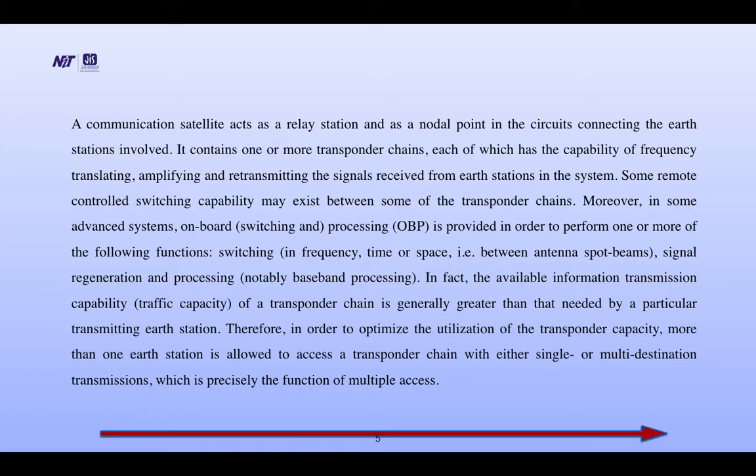Moreover, in some advanced systems, onboard switching and processing, OBP, is provided in order to perform one or more of the following functions: switching in frequency, time or space, that is, between frequency or antenna spot beams; signal regeneration and processing, notably baseband processing.